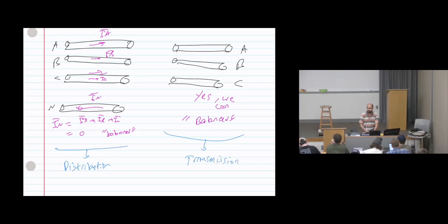And actually, the transmission costs much higher than the distribution, especially with regard to the neutral, because in the distribution, basically it will go for a few miles. For example, inside Auburn, look at the closest electrical substation, which we have close to the stadium, and it's not too far. Or we have one at Dean Road, or one at Sanford. So we have multiple here, and it will go for a few miles at max. It will not go for very large distances. So as a result, we can put a neutral without any problems.